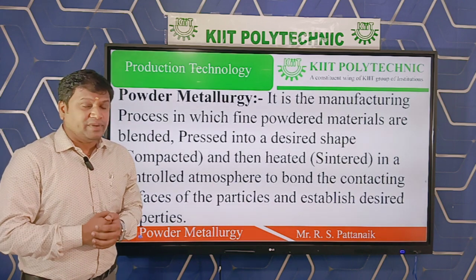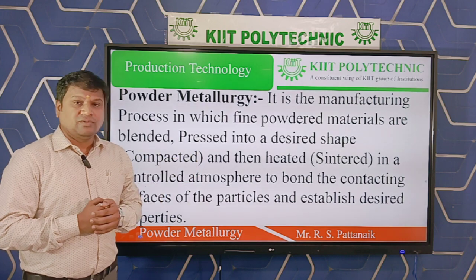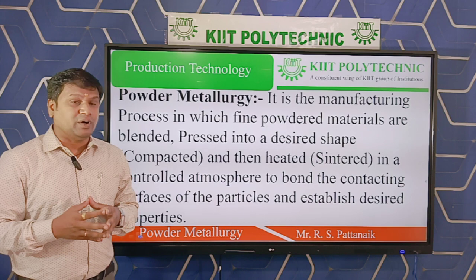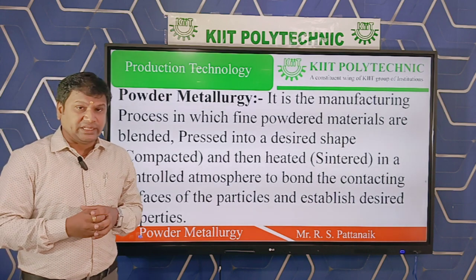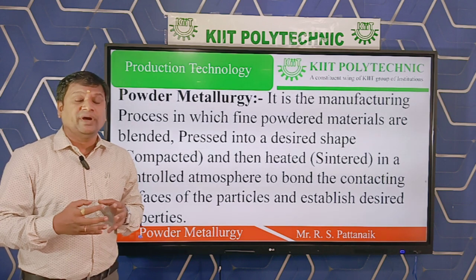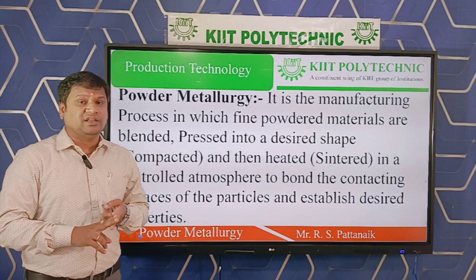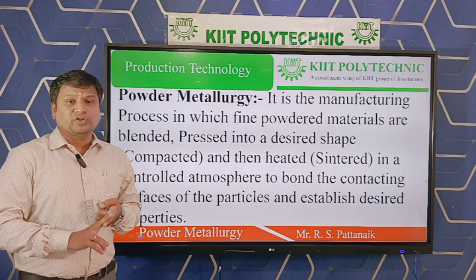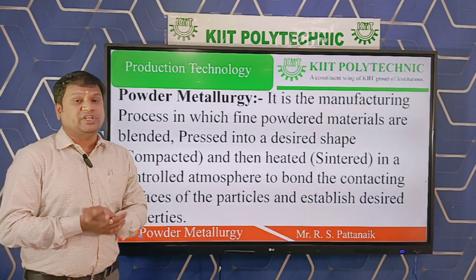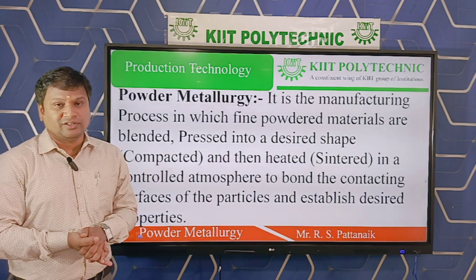There is an important piece of information in the sintering process. When the compacted metal powders are bound together to produce a new product by interparticle bonding, the temperature of this sintering process is kept always below the melting temperature of the base metal. This is the basic principle of the powder metallurgy technique.